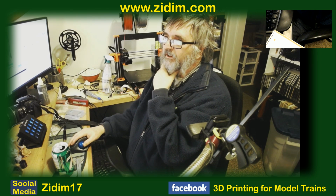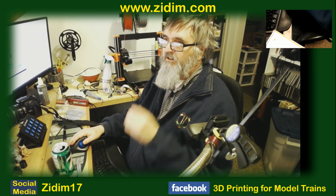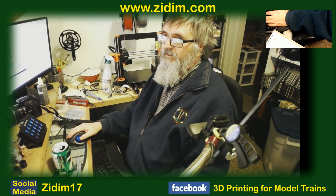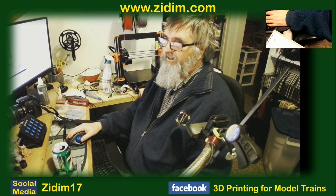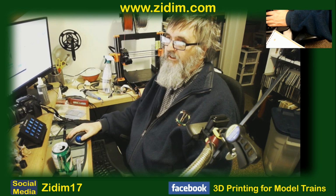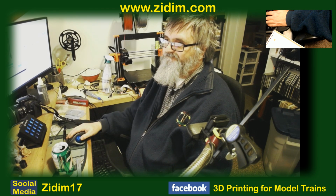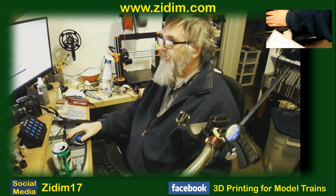I'm going to leave it at 0.2 all the way through. Nothing much to change there. Filament settings, some standard PLA. Nothing else. Infill, 20% is good enough for me. Back to the platter. Slice it.